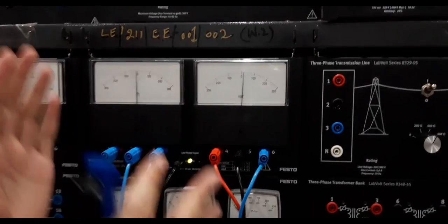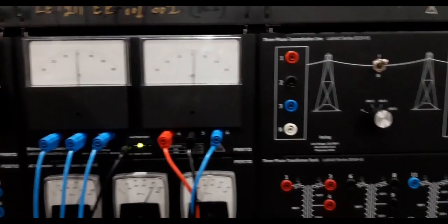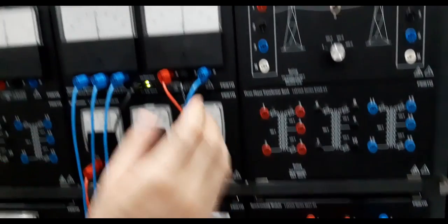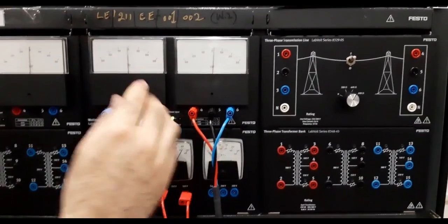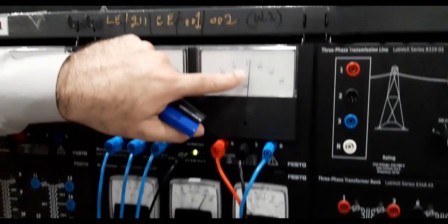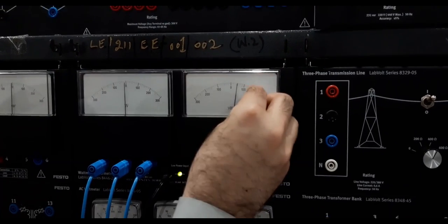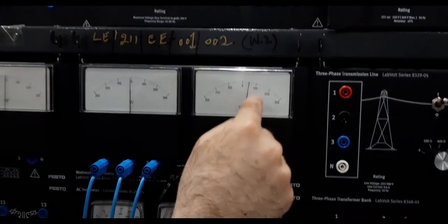And underexcited case is that case where, because the terminal voltage is fixed now, it will not change. But what will change is the induced EMF. So if I now reduce the excitation, the induced EMF will reduce, and if the induced EMF reduces, it means that the machine or the generator will now consume the reactive power. So look here, if I reduce the excitation, one can see here, you see the reactive power flows in that direction and it indicates the consumption.